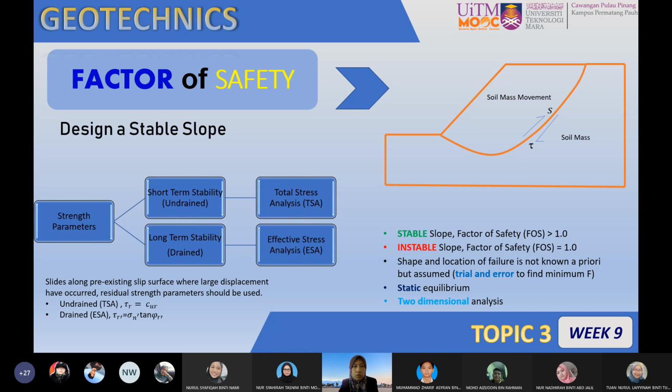And then when we go to the next one, it also explains the mechanism of how the slope fails. Look at this one, the moment of soil weight W. The rotation of the slip circle due to this weight of the soil mass is called the disturbing moment, due to the disturbing force coming from the weight of the soil multiplied by the lever arm, or perpendicular distance where W is at.